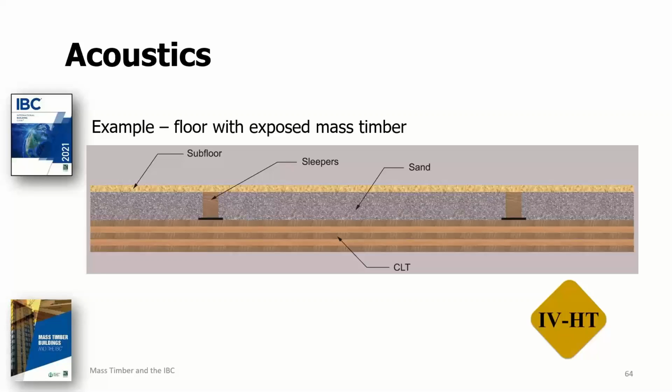Also, these serve to provide some sound absorption as well. And then another form of decoupler could be sound clips on the ceiling side, either sound clips or resilient channels on the ceiling side to which gypsum wallboard could be attached.